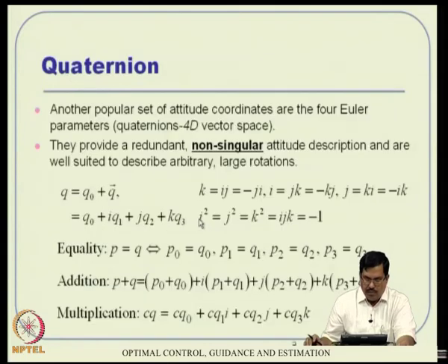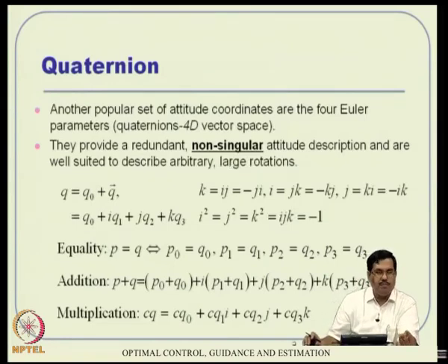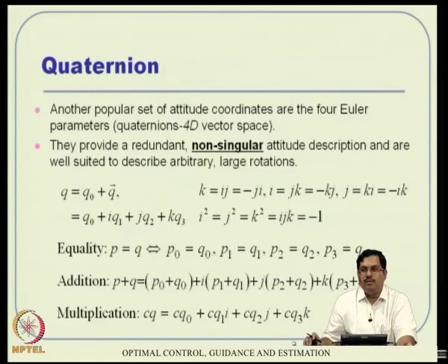Okay, so finally let us talk a little bit about quaternions. Quaternions are essentially to get rid of the singularity problem. Unfortunately, anything that you use, either direction cosine, Euler angle, modified Rodrigues parameter, whatever you use, all these three-parameter representations suffer from singularity. It is a matter of where the singularity occurs, but it has a singularity. Now, can we talk about a singularity-free transformation? That is where this quaternion algebra is useful.